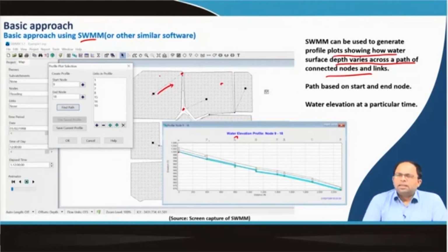And in each node there is a manhole, because there is a change in direction or alignment and so on. So, we can see the volume of water in each of these sections, and this could be determined in SWMM. Based on the rainfall event that has happened, we can run the simulation once we have put in all the data, and we can determine the volume of water in each of the sewer sections.